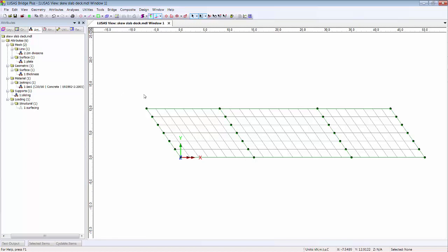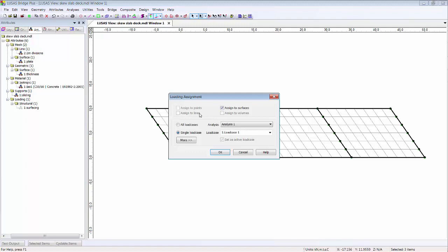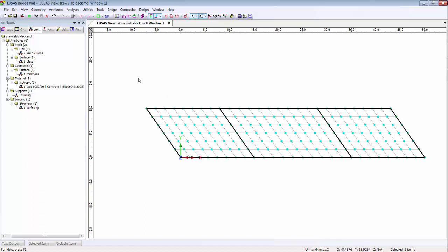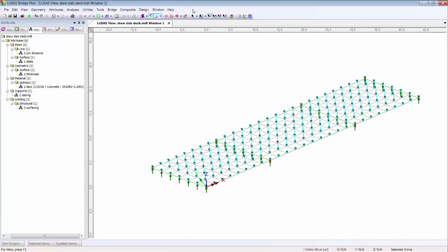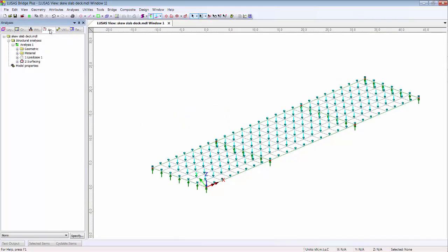Anytime you see those numerical inputs, you can use a kind of expression of that form. And if I just choose the surfaces where that applies once again, and I drag and drop my surfacing, I can put that into a load case. Let's put it into a load case called surfacing, in fact. And I can see little blue arrows. If I rotate around, you can see the blue arrows pointing downwards, which is a good sign. And if I go to perhaps my load case, I might wish to call this my dead load. And I can add gravity just like so.